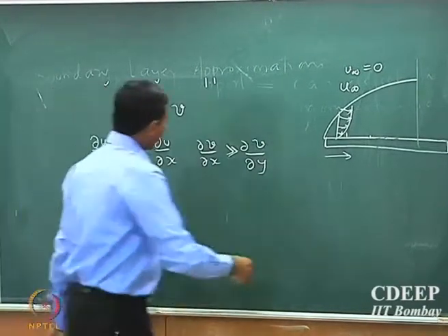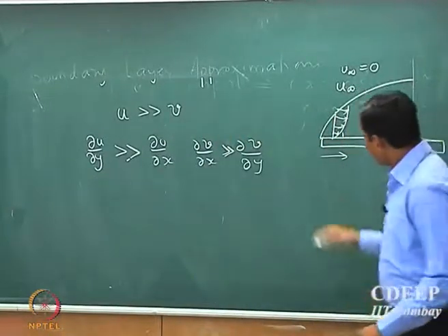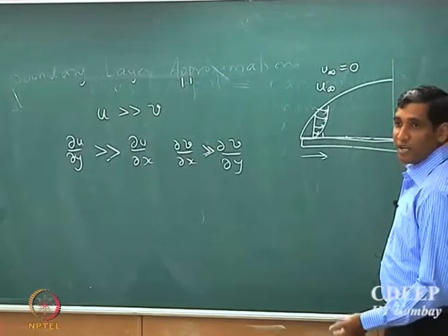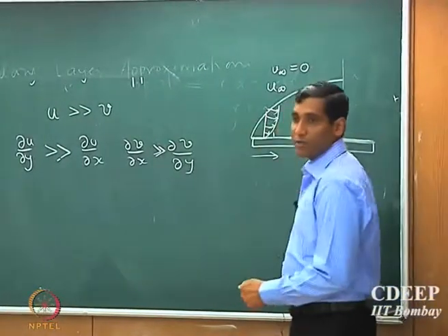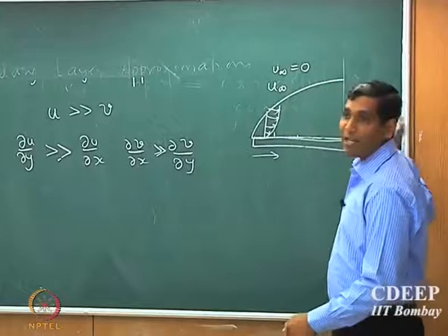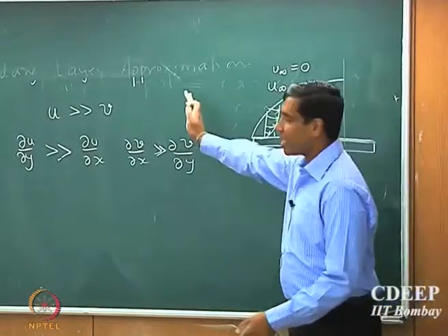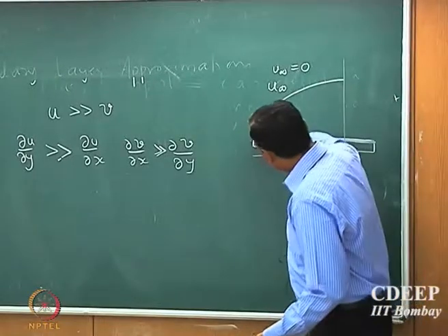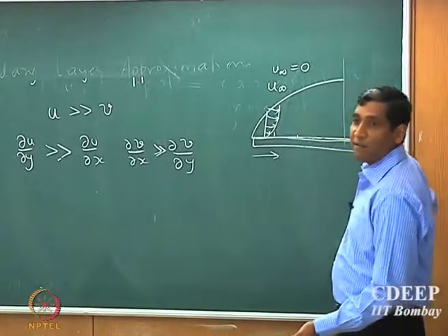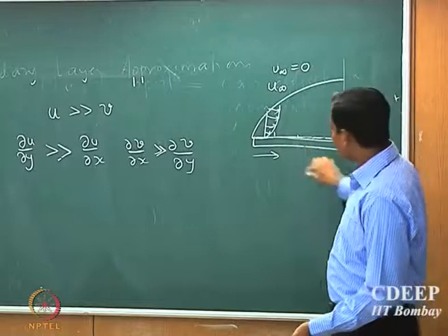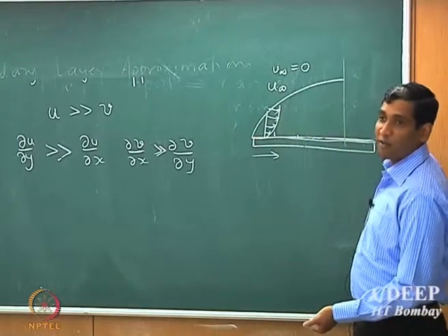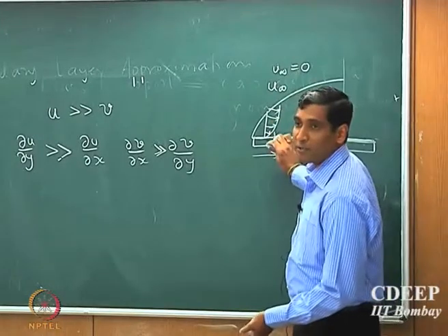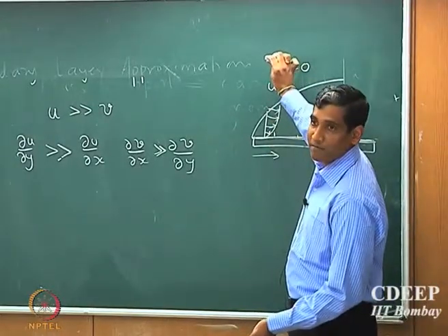So supposing you take, so the wall is present here, right? So you have an interface. Now when the fluid is moving in the x direction, so the pressure gradient is primarily in the x direction, right? Because that's the direction in which the fluid is being pumped. Now as soon as the fluid sees the flat plate, it is exposed to the friction which is offered by this surface. So therefore it is going to retard the fluid particles above it in the y direction, right?